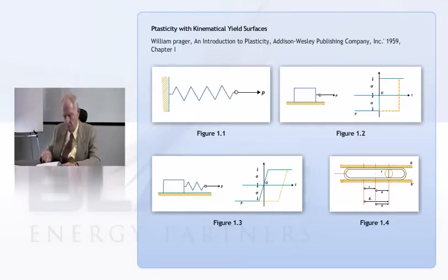And what he's saying is that if I start from where he's showing the stress is 0 at the bottom there, you go through an elastic region until the pin hits the slotted plate, and then you move the slotted plate, and when you move the slotted plate, you move its whole length. So when you try to bring the pin back, you can come back twice as far as you went from the 0 stress, but that's all.